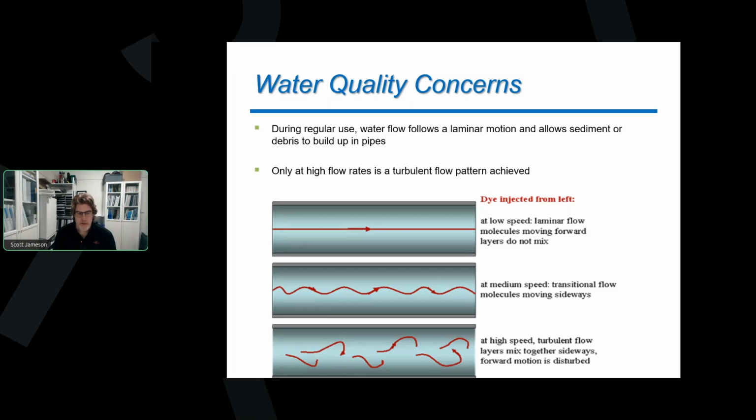And we want to get the water rushing up against the edges or the ends of the sides of the pipe and hopefully grabbing any debris that might build up there and dragging that along and down the line, and maybe tearing off any biofilm or slime that is growing on the sides of the pipe. So, with a UDF program, that's really what we're targeting. We're targeting this idea of trying to maximize the velocity we can achieve within the pipe while we're doing our flushing.